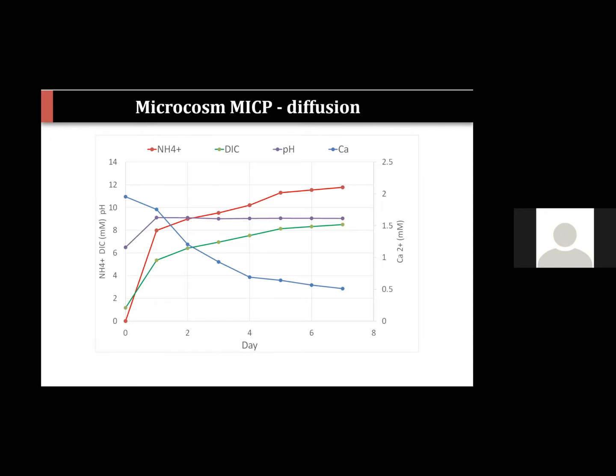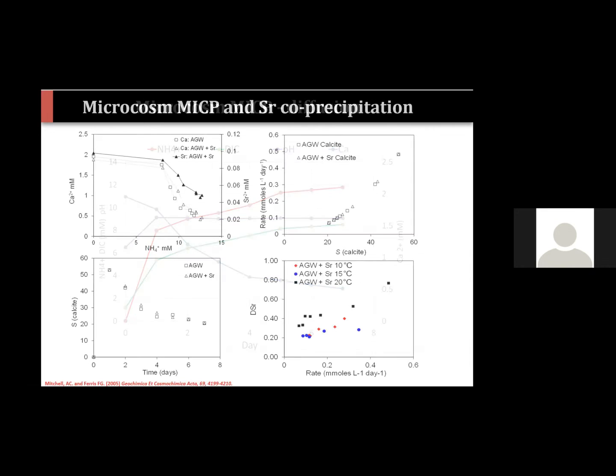And as I mentioned, this mechanism offers a way to form carbonates in rather hard to reach subsurface zones, because it only requires low viscosity fluids, and controlled gradual precipitation avoids the inlet plugging issue that we would have if we were using simple chemical mixtures.